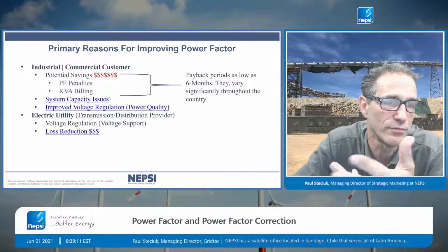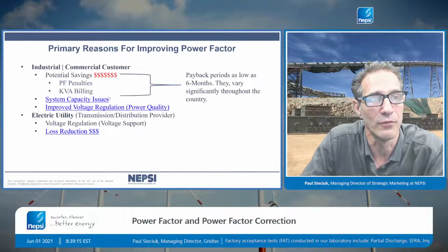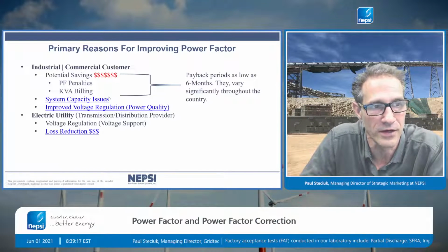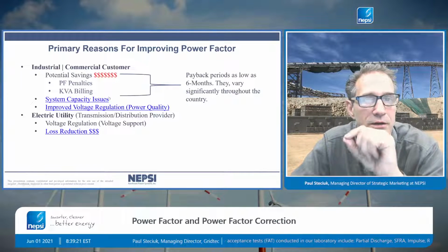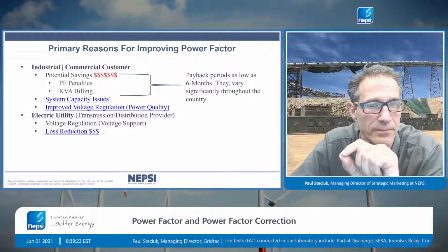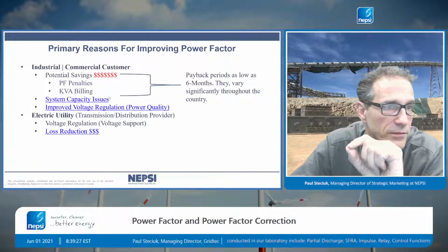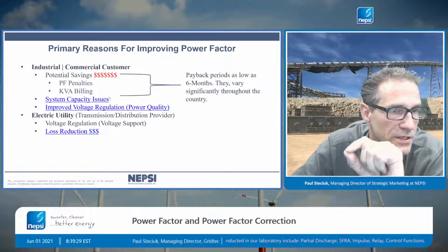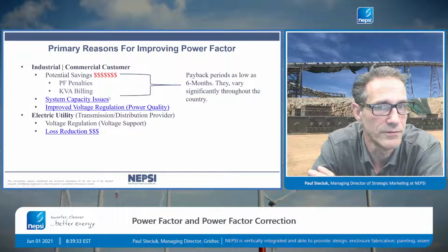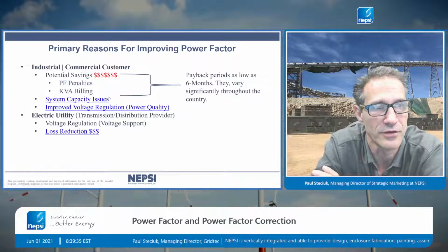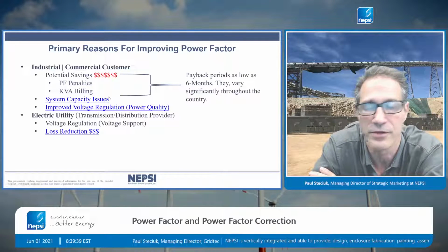So if the power factor is 0.8, they divide by 0.8. So the customer indirectly pays for more KW because its power factor was not 1.0. So oftentimes you'll see KW demand divided by the power factor of the system, a 15-minute average or peak, maybe 15-minute average at the peak time of the day, will give you the new KW demand charge that the customer will see. And that can oftentimes be very, very expensive.